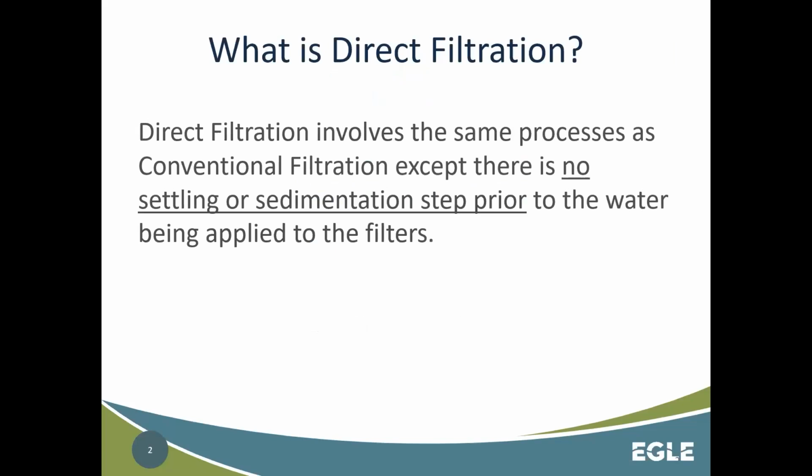Okay, so what is direct filtration? Direct filtration involves the same processes as a conventional water treatment plant, except there's no settling or sedimentation step or clarifier step prior to the water being applied to the filters. So the name is pretty self-explanatory.